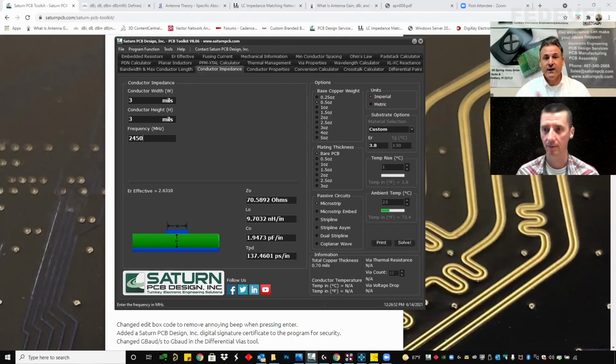Okay. But even the Kappa 438, I modeled that. I got the dissipation factor. I got the dielectric constant. I simulated it, and it was 15 to about 11 megahertz off. So I'm calling Rogers and saying, what is the exact dissipation factor at that frequency? And that's another thing that can happen: you look at the data sheets, and the DK might be measured at 1 gigahertz or 10 gigahertz. If you're running at 400 megahertz, those numbers might not be accurate for you.